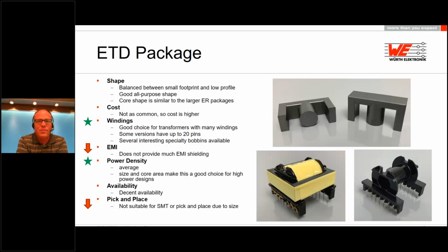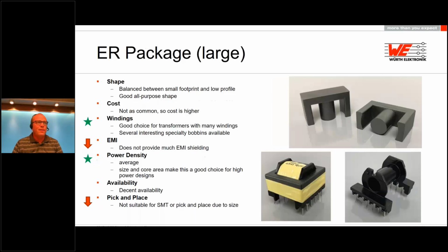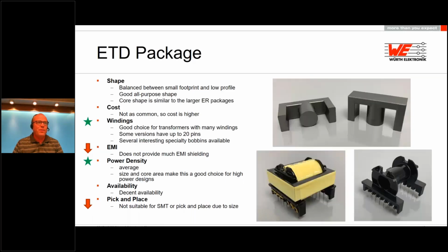All right, so next up is the ETD. And really it's very similar to the larger ER packages. And if you compare the core shape between the 2, you'll see it's almost identical. So like the ER, these are a real good choice for higher power applications.